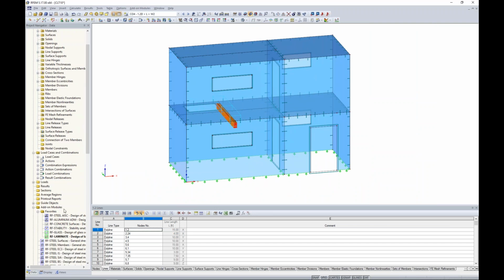Now, actually, one more thing I forgot. Remember within the PowerPoint, I said that we should really set the FE mesh for torsion when we're doing torsion checks approximately equal to the plank width for each individual CLT layer. So for my wall elements, I need to adjust my FE mesh. We do have FE mesh refinements in the program, so I can individually change each wall panel's FE mesh.